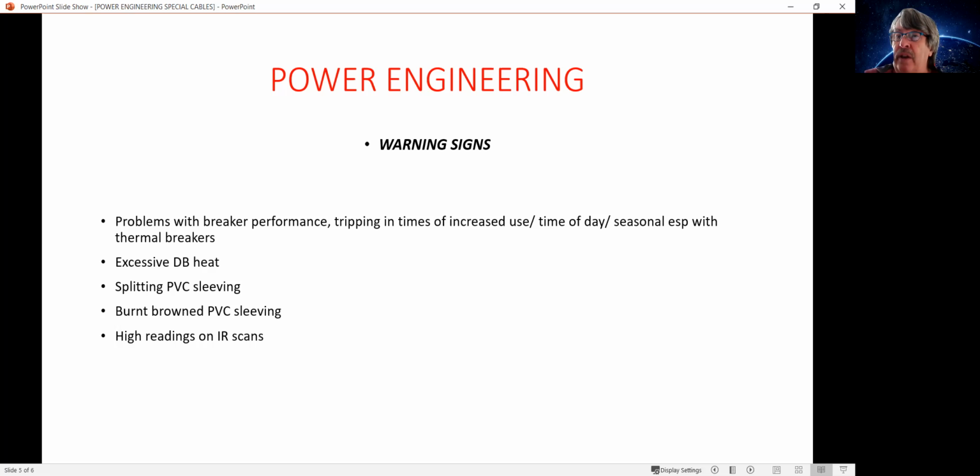If you have PVC on a lot of the conductors inside that panel, you will see that it will dry out and split. Not a good idea over time, as all your insulation starts to peel away and peel off. You sometimes see that the PVC browns and starts to discolor. It's not really a burn as a fire, but over time it loses all its elastomers and becomes brown and looks as if it's taking heating type readings.